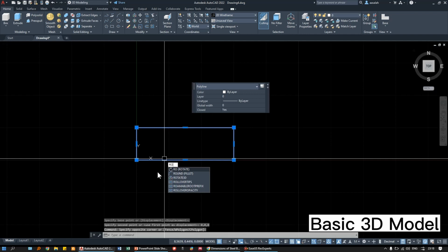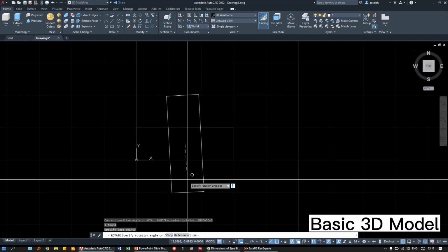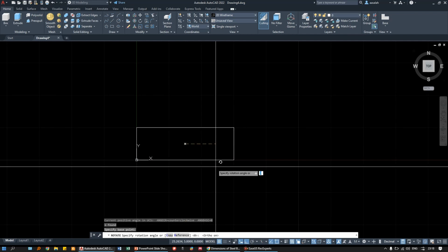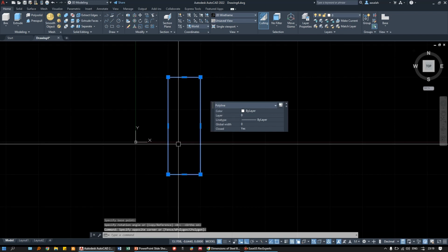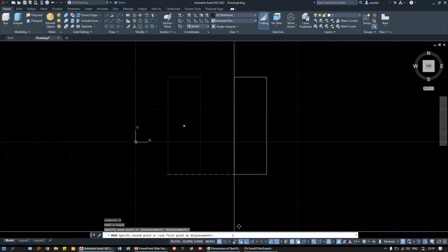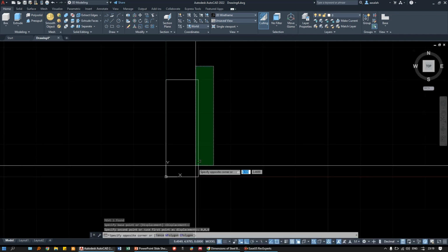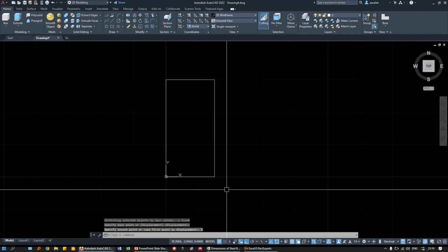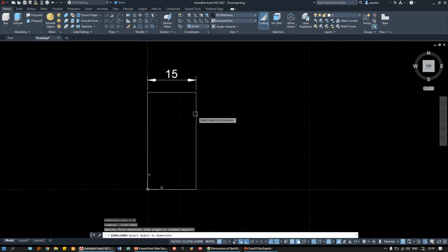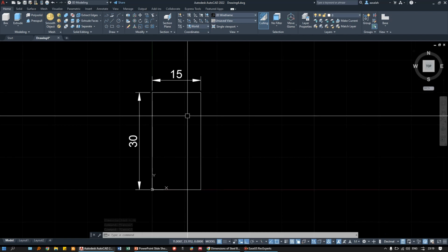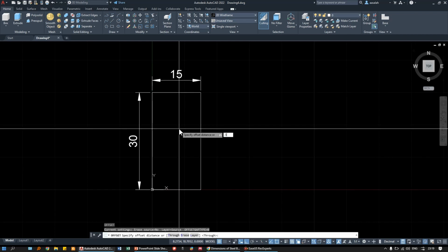As I can see, I can also rotate it by using rotation command RO. And I'm gonna click on this option to make it orthogonal, which is F8 shortcut, which allows me to rotate stuff into 90 degrees. I'm gonna move it again to make it at the origin, 0, 0, 0. So this is my I-beam. I can expand it. Let's make it 15 inches in width. If I check, 15 inches by 30 inches. So this will be the dimensions of my I-beam. Let's assume the flange width to be ½ inch. So I'm gonna offset this into ½ inch.